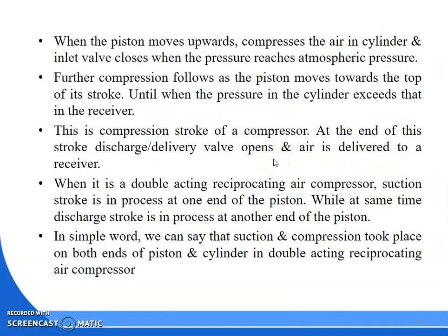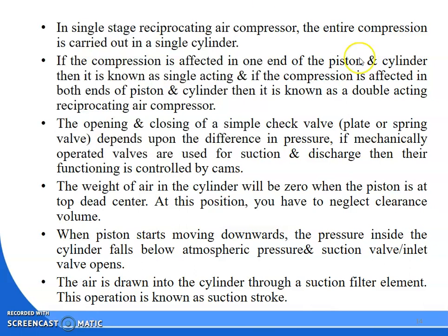These are written here. So next, what will happen? So what is the working? In the single stage reciprocating air compressor, the entire compression will be carried out in a single stage. The compression is effected on one end of the piston cylinder, so it is known as what? Single acting.